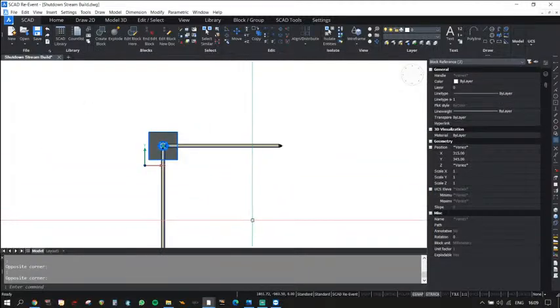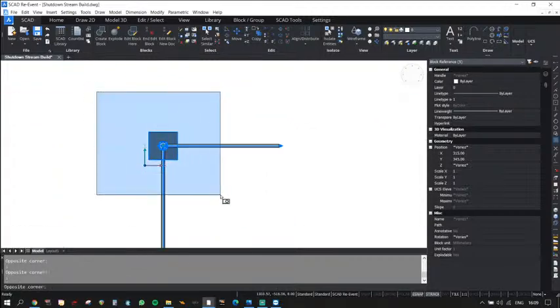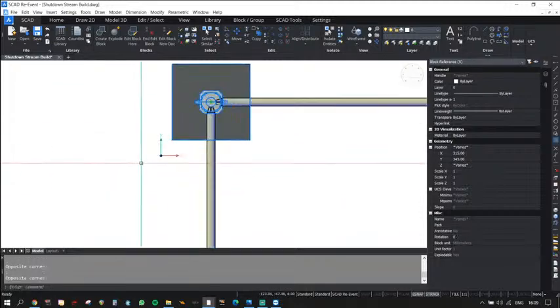If I drag it from right to left, it will select everything that is inside the box, and from left to right only the full object that is surrounded by the box.